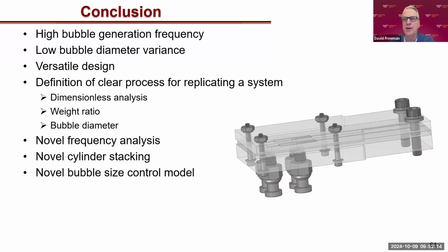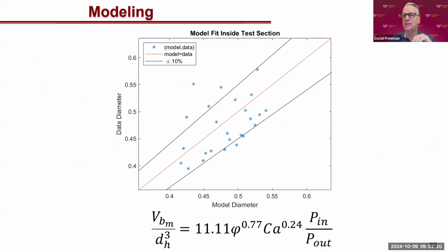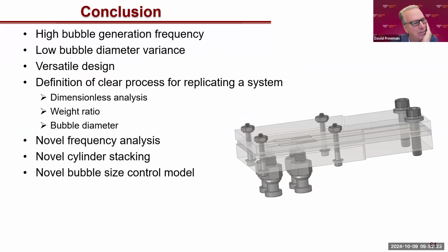Okay, and then for bubble size, you used a metric, maybe on the previous slide, like 6.8%. Was it variation? What was the metric? So that was percent standard deviation. I misspoke, and I also put it on the slide improperly. We took the standard deviation of all of the bubbles generated in each test, and then we calculated the percent standard deviation by dividing that by the average of all of those volumes.